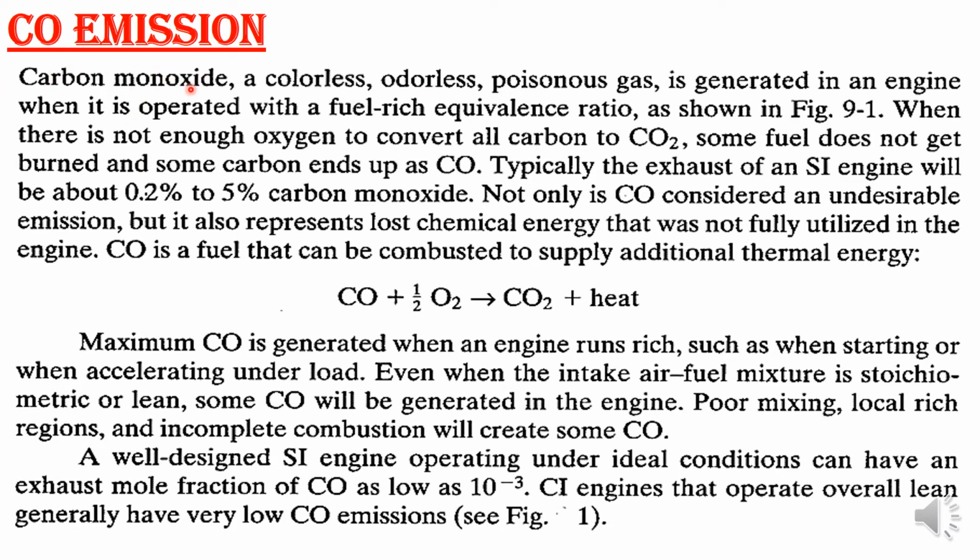So theoretically, the gasoline engine exhaust can be made free of CO by operating at an air-fuel ratio greater than 16:1, that is on the lean side. However, it is clear that CO will always be present in the exhaust even with a lean mixture. A small amount of CO will always be there in the exhaust. We can't avoid it to 0% of CO. CO will be there because sometimes dissociation will take place.